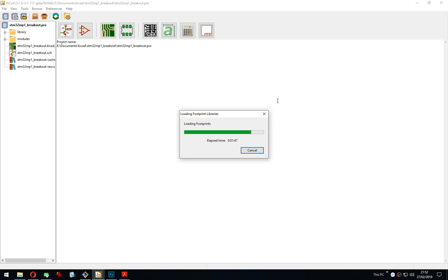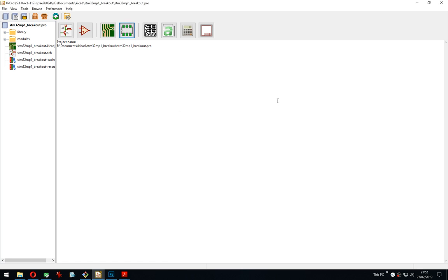Yeah, KiCad has a QFN generator, BGA generator. They are just very well hidden because UX is not for engineers. I didn't even know you had any sort of generator. I've always drawn things by hand. Yeah, from scratch. I also learned the hard way that actually there are generators.